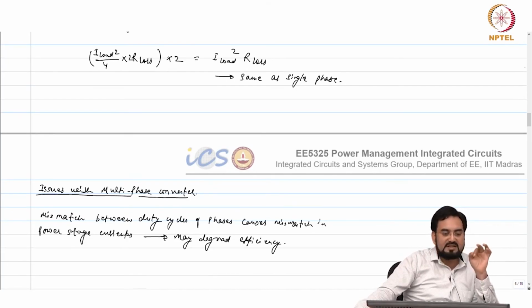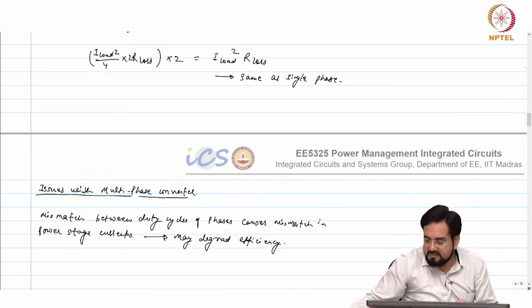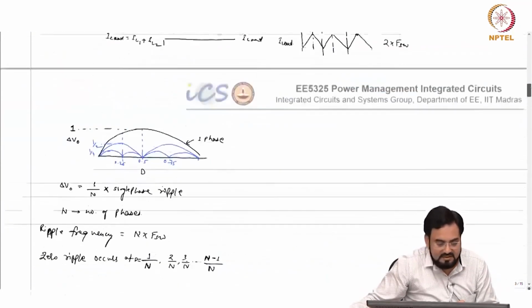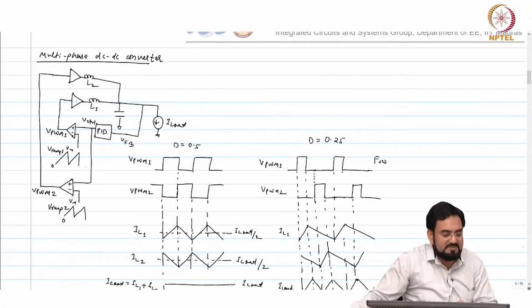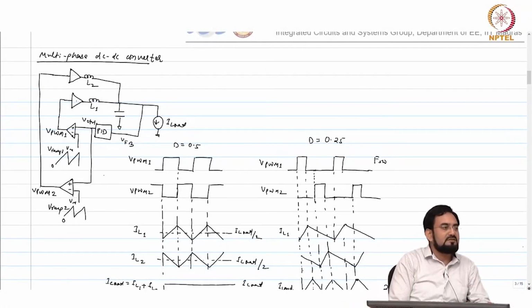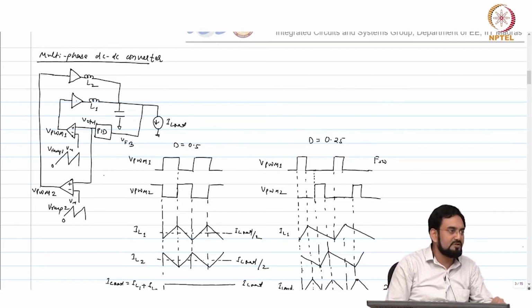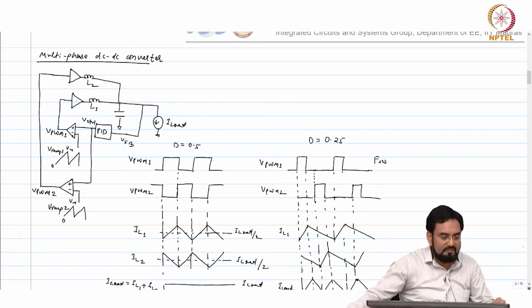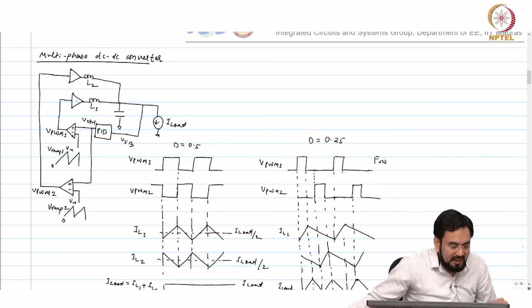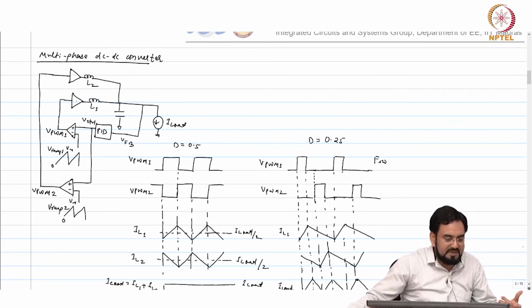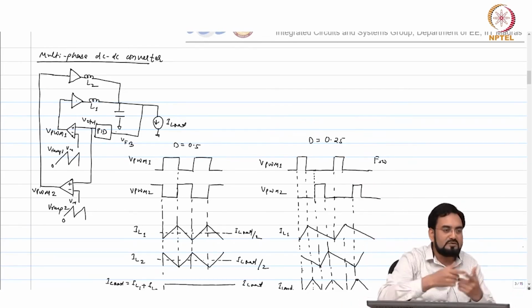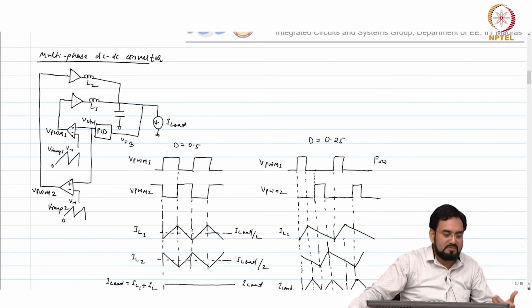So, we are using a single control voltage. Who will cause the mismatch here? Ramp will cause the mismatch, or comparator offset, or let us say delays in the comparator, that will also cause mismatch. And ramp, obviously, since we are charging a capacitor with a current, and those two currents may have a mismatch. That is why we require current balancing.